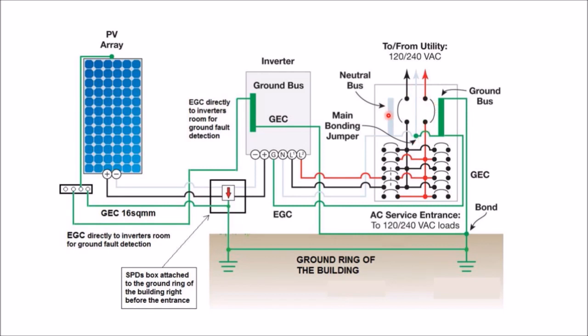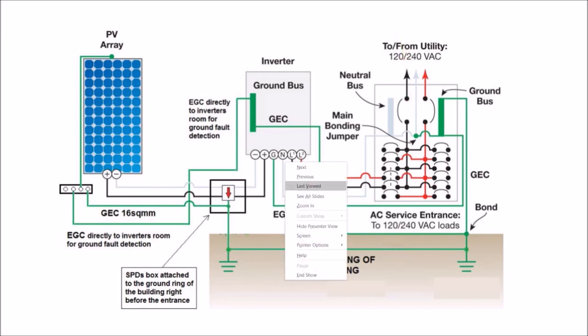But that might be in the meter base rather than in the service panel. And so here we have a combo meter panel box with the main bonding jumper being made in the box itself. If you remove the meter panel from your main service panel, this bonding jumper point will likely travel with the meter up to the utility service disconnect at the meter itself.